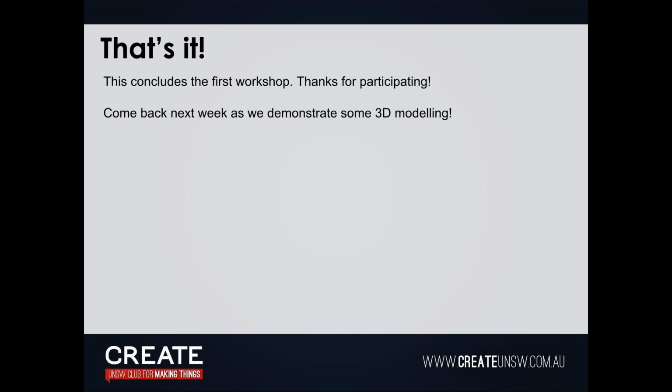What else do we have here? Just for this purpose, I'll go into one or two of the 3D tools. The main thing, if you want to 3D print this, is you extrude it. Extruding is just lifting a flat surface into an object. So you hit create, you select what you want to extrude, and we'll say about 5 millimeters. You hit OK. Now I probably can't notice it from here, but that is extruded now.